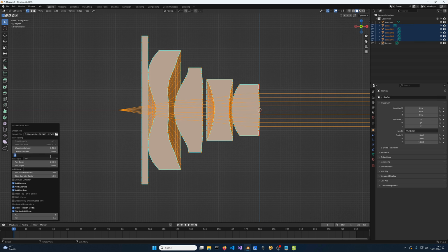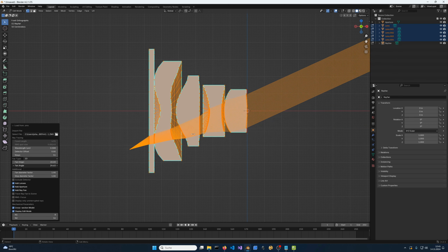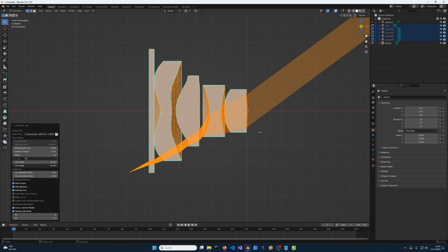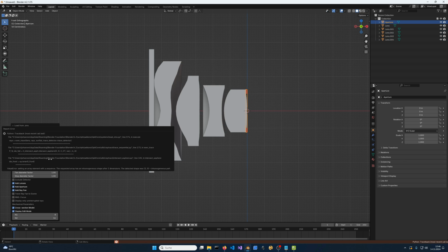Other than that, if we look at a ray fan, this lens is designed pretty similar for a similar field of view of around 30-35 degrees. When we increase the angle, we can see we're still vignetting free up to this point. And again, some vignetting at the lens edges starts to take place around 35 degrees. Then for this lens, there is a really rapid fall off at just over 38 degrees, where it's already fully vignetted.